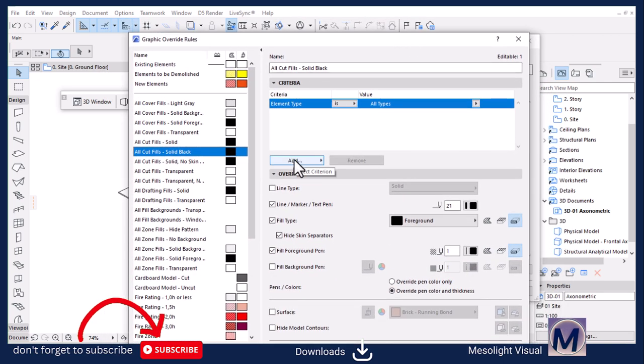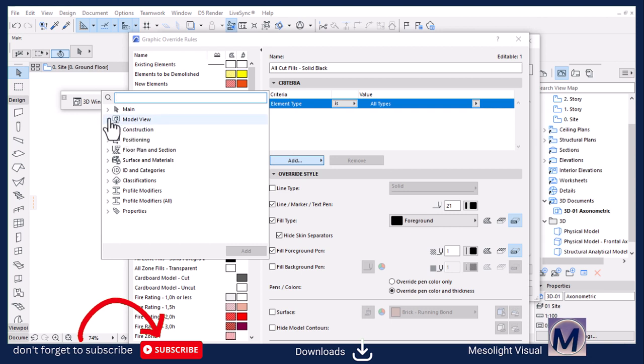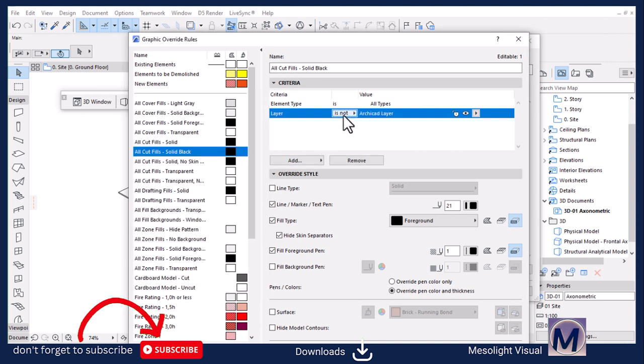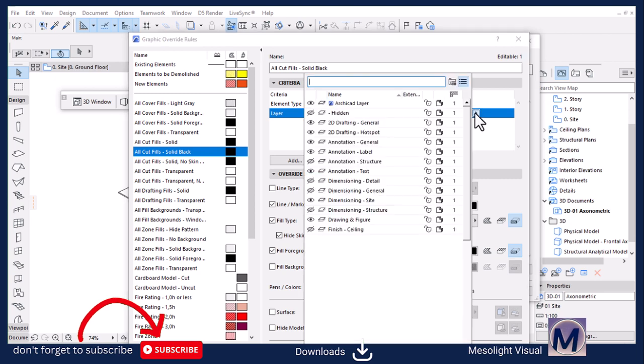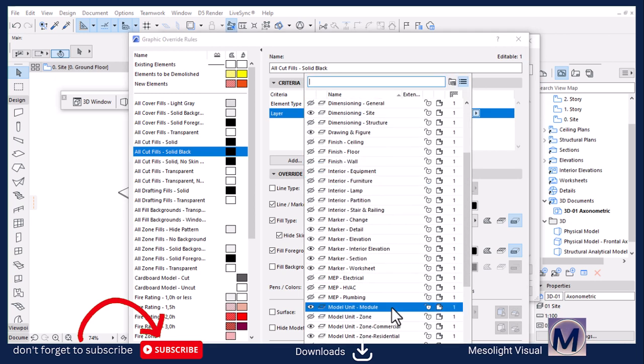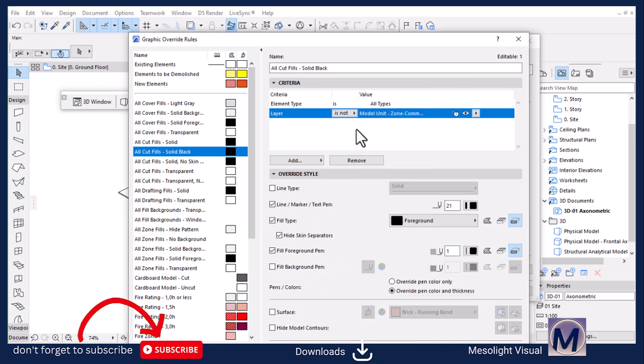So let's add a criteria that uses a layer under model view. Let's add that layer, and then we say it's not, because we're excluding it from this overriding style. And then we're going to key in that layer. It's going to be commercial, and then we hit OK.